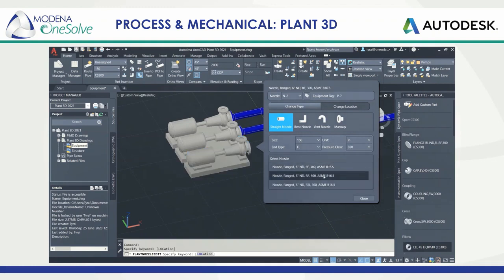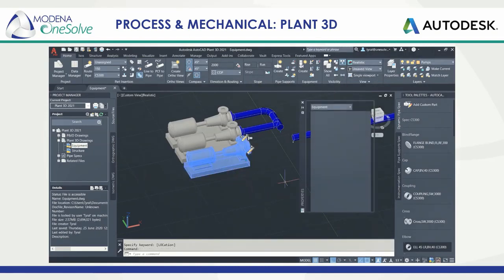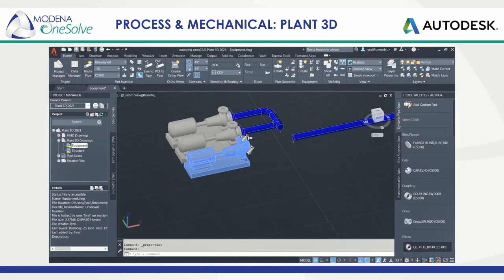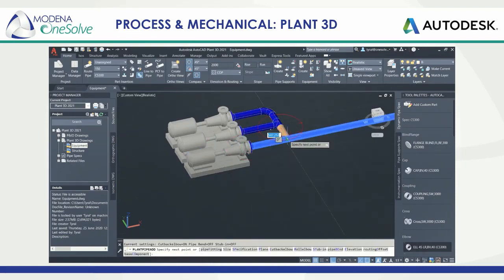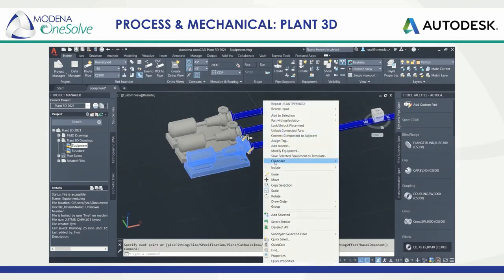The property information from Inventor translates to Plant 3D, and you should see that coming up on the screen as well. So there you'll see, as I scroll through the properties quite quick, you can see how the property information has come through on the manufacturer side, as well as in the short description of that component. This behaves as standard Plant 3D equipment, and we can route piping from here as well.